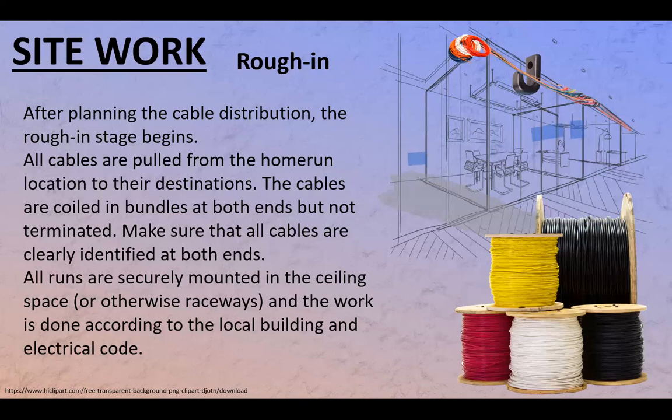Time consuming. As I said, the best window of opportunity for us to get our wires in is before drywall gets installed. And here's the important thing: after the air duct people are gone, they've done the job and they're gone. Because if you are working at the same time or before the air duct people are doing their thing, your cables are most likely to suffer some sort of physical damage.